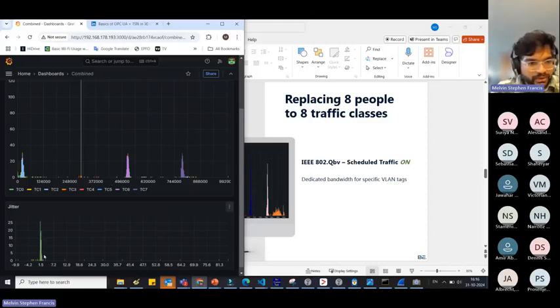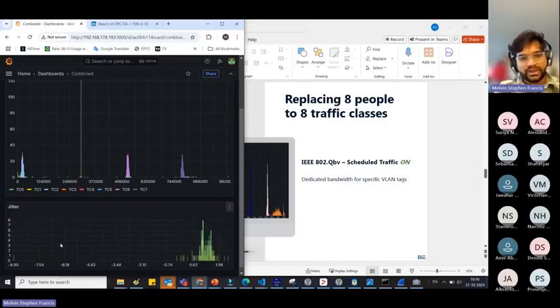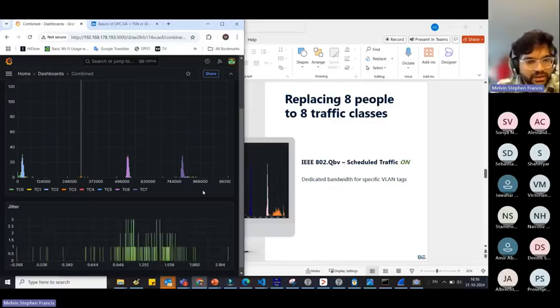Okay, and also the jitter is plus or minus 4 microseconds, and this would say that OPC UA pub/sub over raw Ethernet is, so now you can see it is getting better because I started it. So it is even plus or minus 2 microseconds. So it's also in the nanosecond. So most of the packets are in the nanosecond range and some are spilling out here. So this test suite proves that our OPC UA packet is able to be delivered on time.